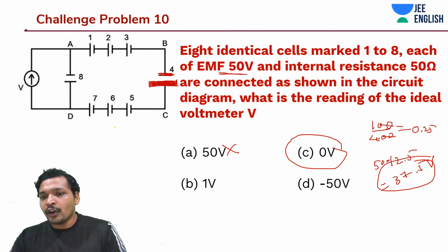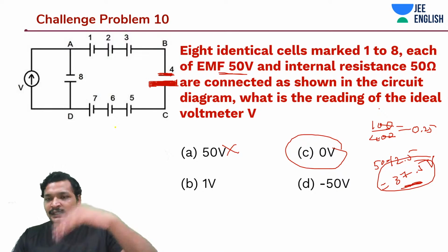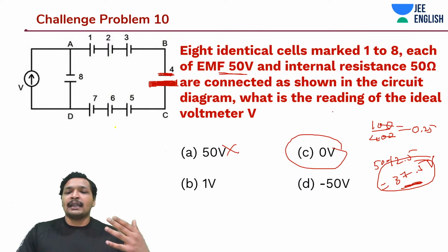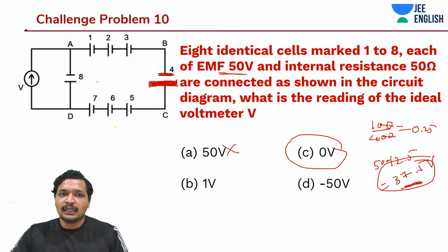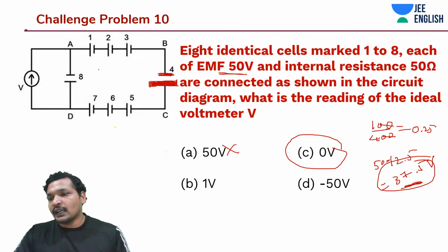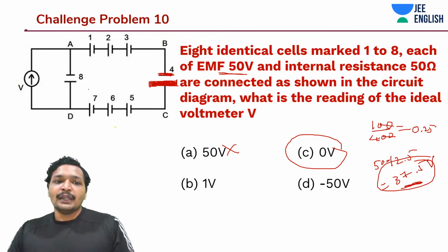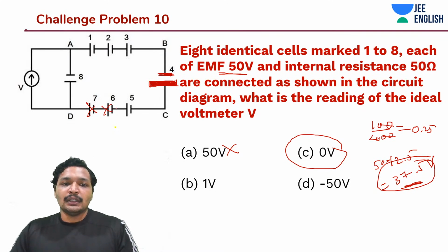Else you go by Kirchhoff's law and you will get the answer as 37.5 volts, because the 8 resistances are in series and are not cancelling out, only the voltages are cancelling out. There would be a terminal voltage across each battery due to their internal resistances. This and this only will cancel out in the original problem, if I'm moving around the loop like this.